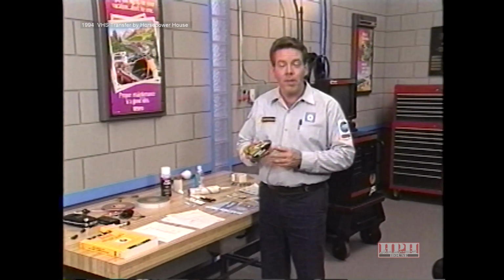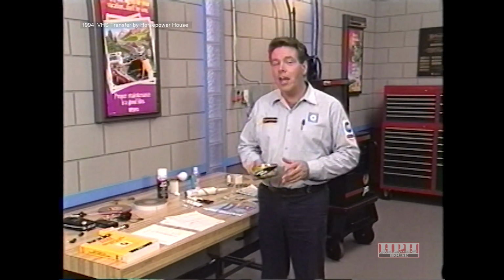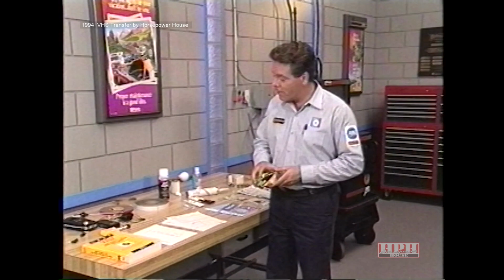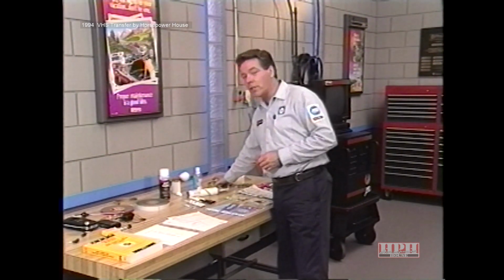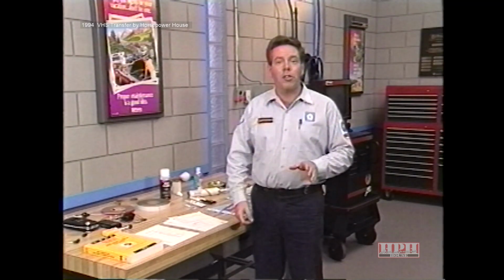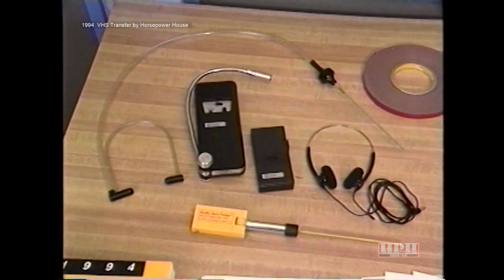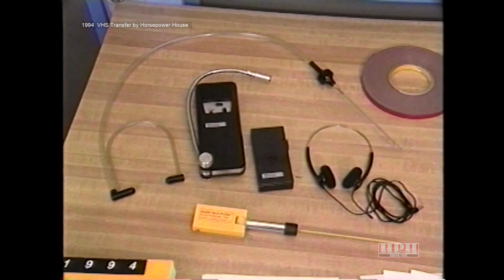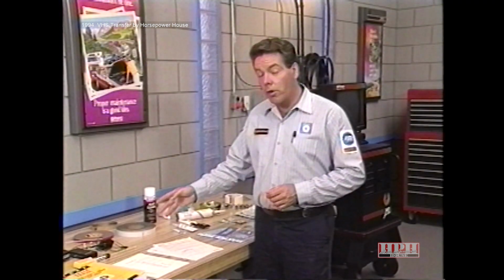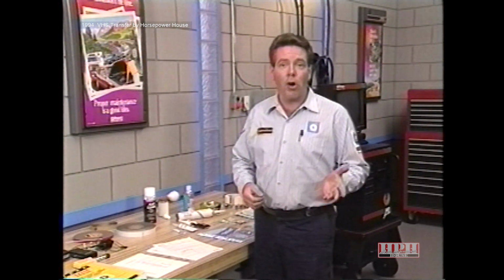Next is a test that is very helpful in locating small leaks, the heater blower test. The main idea here is to use the heater to pressurize the interior of the vehicle. This allows you to use an electronic leak detector or an audio tech probe, both available through professional service equipment. You can also use a stethoscope to locate holes or gaps around the door and window seals, which may be causing wind noise or water leaks.